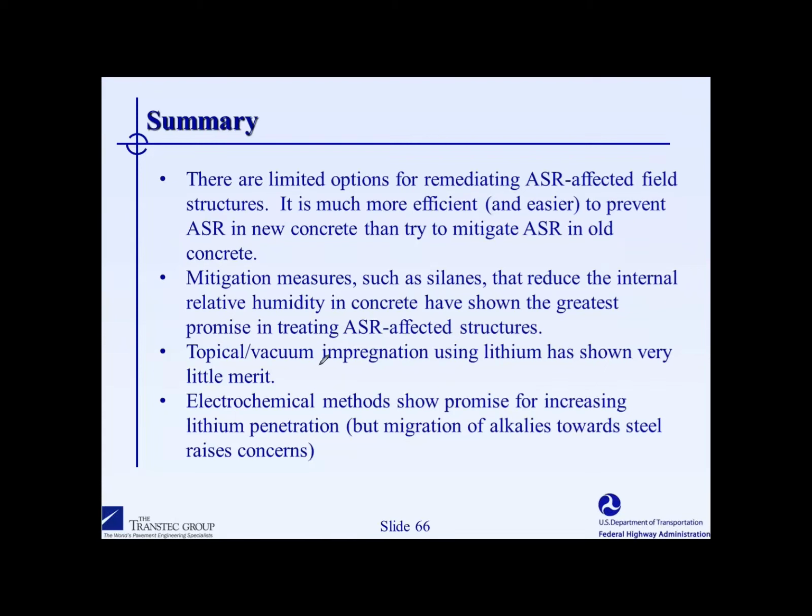With regard to the lithium applications, we really didn't see much benefit at all, and very little depth of penetration for topical and vacuum impregnation of lithium. So it doesn't really seem to show much promise in the lab or in the field. The electrochemical method does show potential, and we were able to drive lithium all the way to the surface of the steel, but again, the issue that needs to be considered is the migration of the internal alkalis that tend to move towards the steel once that current is applied.